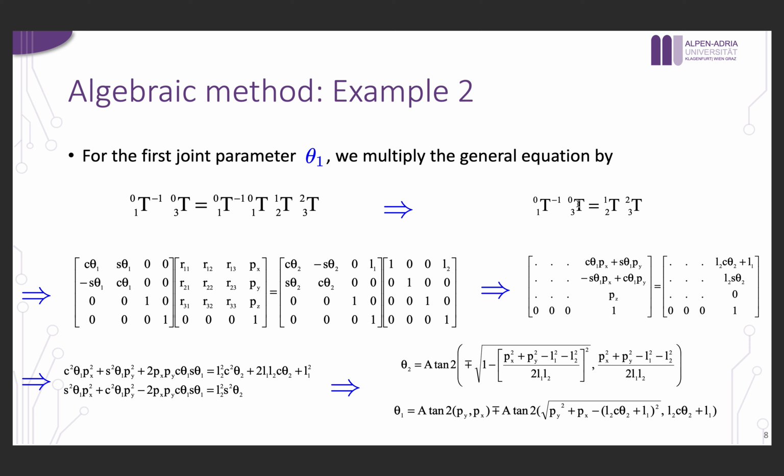So we would end up with these two sides of an equation, and this is how they are presented. We are multiplying this with our transformation matrix, and this would be on the right side. So we would have a set of equations, and what I want to find is a set of equations where, if theta 1 is there, that's good. But if I can also find other thetas, for example, if I can find two equations like we see here, where theta 1 and theta 2 are the only unknowns in these two equations, then I can solve it, right? So this is what has been done there. You see that they derived these two equations by just multiplying these two.